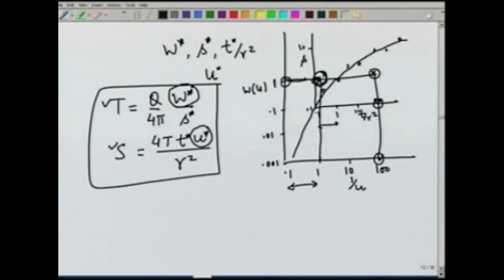So, we have seen some methods of estimating the parameters S and T, for example, Jacob's method which required data for very long time. Then we have Theis type curve which can use all the data set and compute the values of S and T. We have also discussed all these methods only for confined aquifers. Unconfined aquifers are a little more complicated because the thickness is not constant, it depends on the head h, and we will have to make some simplifying assumptions to obtain the equation of motion. That we will do in the next lecture.